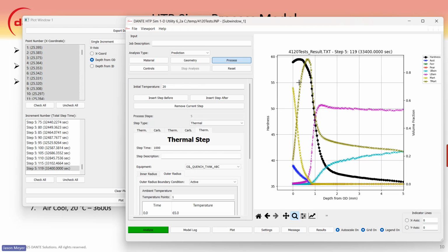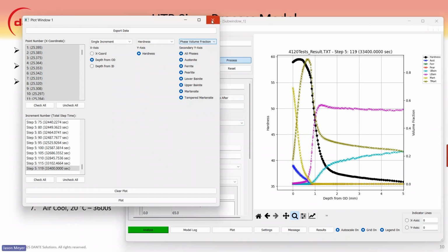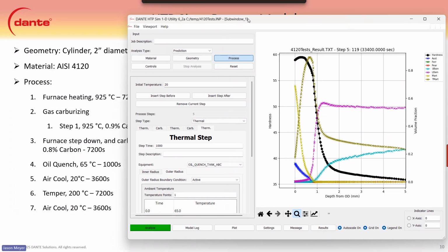Since we have tempering on, this is auto tempering, so this martensite transforms relatively early at a higher temperature, and then it quickly auto tempers in this region to go to tempered martensite instead of standard gas quench martensite. All right, so that is the quench process and the post-processing for that.